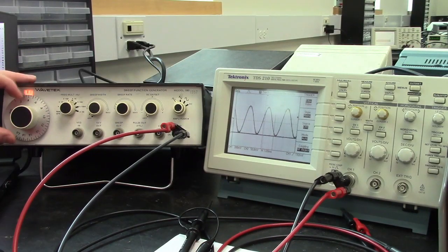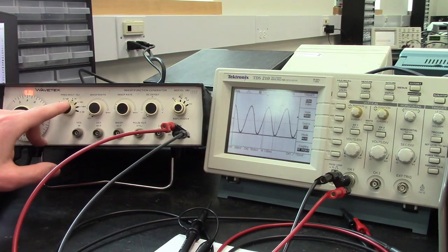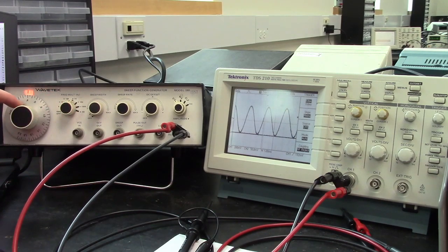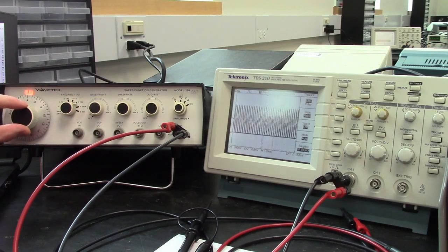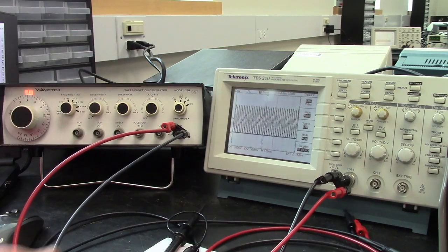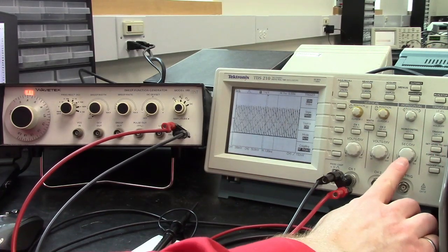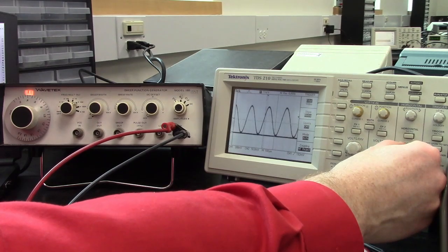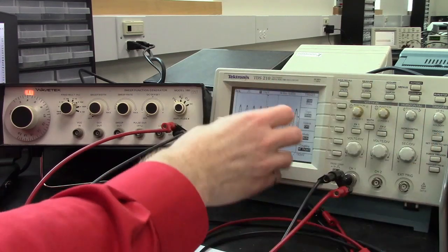There's a couple of different ways to set this. First thing you can do is get it to the right kind of ballpark by setting the frequency range on the function generator. So here we're at the 1 kilohertz, so this is at 0.4. What we're going to need is probably around 10 kilohertz and 0.4 here. Now to see this show up again, what you can do is adjust the horizontal position with this dial here, and turning that to the right will sort of widen out the wave.